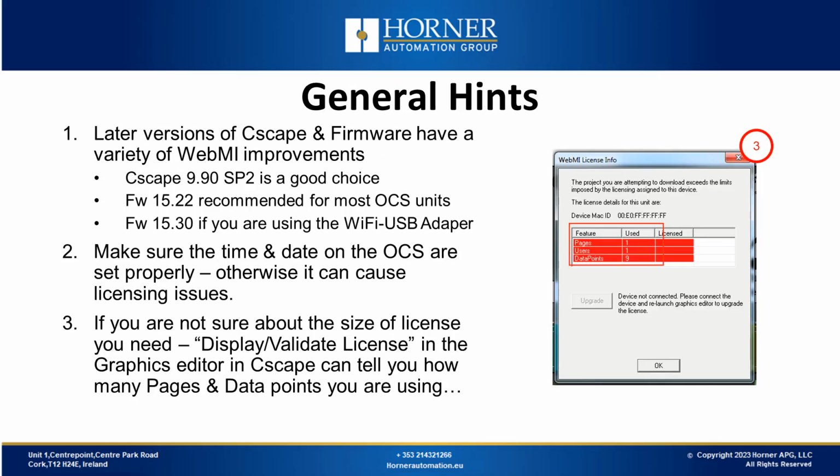Now we'll look at some helpful hints. WebMI has been available for a while, and we've continued to make improvements both on the Seascape side and the firmware side. And so, some of the new firmware will be recommended for making the process work better, as well as including some new features, like timeline control, for example. Another point I should make, if your time and date on the OCS are inaccurate, sometimes that can trip up the licensing, even though the license isn't necessarily time-based.